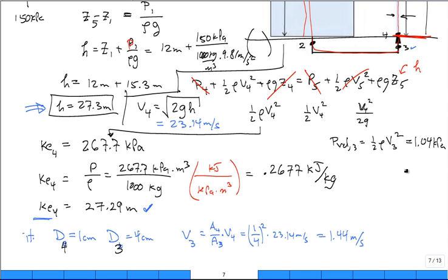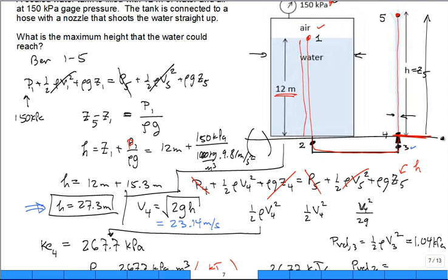All right. So what's the velocity pressure at 2? The dynamic pressure at 2 is the same as the dynamic pressure at 3. It's very small, almost negligible in Bernoulli's equation. So what's now the pressure? I know I'm asking a lot of questions. I'm trying to move a little faster.